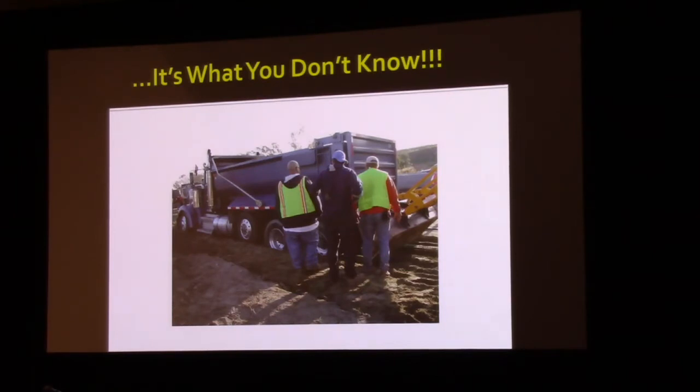But of course, with every good project, no matter how much planning you do, there's always going to be something that goes wrong. How do you prepare yourself to handle that? In this case, during the full depth reconstructed areas, they ran into some very wet, expansive clays that, when they started to pull the slabs out, the clay came out as well and puffed up. This was during one of their 55-hour closures, so they had time to figure out what happened and how they were going to address it, because this was the first of many of these.